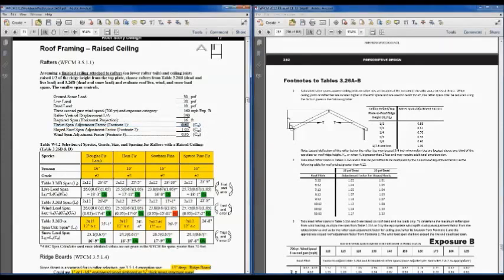penalty on your span. And again, you can see it here in the wood frame construction manual graphic in this workbook, where that rafter gets raised up into this attic space. We're putting a lot more load in the rafter at this location because of the increased moment here. So not only are we resisting the snow loads or the wind loads on this rafter, but because we've moved this tie up into the rafter system, it puts increased moment here, and so that's what this penalty is on the span.